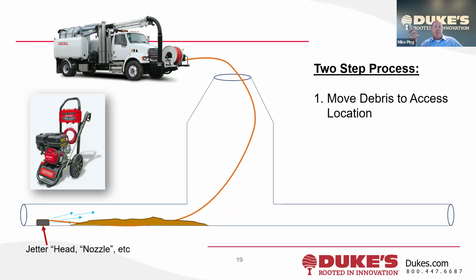And a lot of times the operators, there's usually two, they may pop the next manhole and look, and he's waving to his colleague over there and saying, hey, the jetter's up here at the next one. And at that point, the controls are up here next to the reel, and the operator may hit the switch or whatever mechanism, and it hydraulically pulls this line back, mechanically pulls, I should say. So it deploys sort of on its own. It gets pulled back by the hydraulics that are built into the reel system up here.